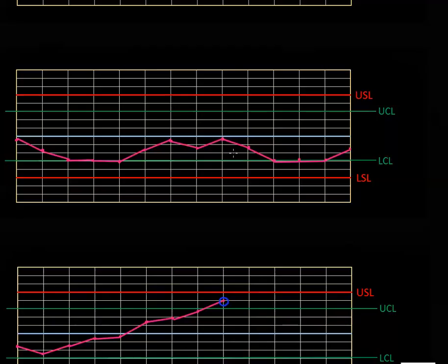It looks like it's random, down, and then flattens out. Maybe it's a recurring pattern, right? Maybe it's a shift, but for some reason, between here and here, right at our lower control limit, it suddenly flattens out, okay? In other words, it lacks variability, but only in certain spots.